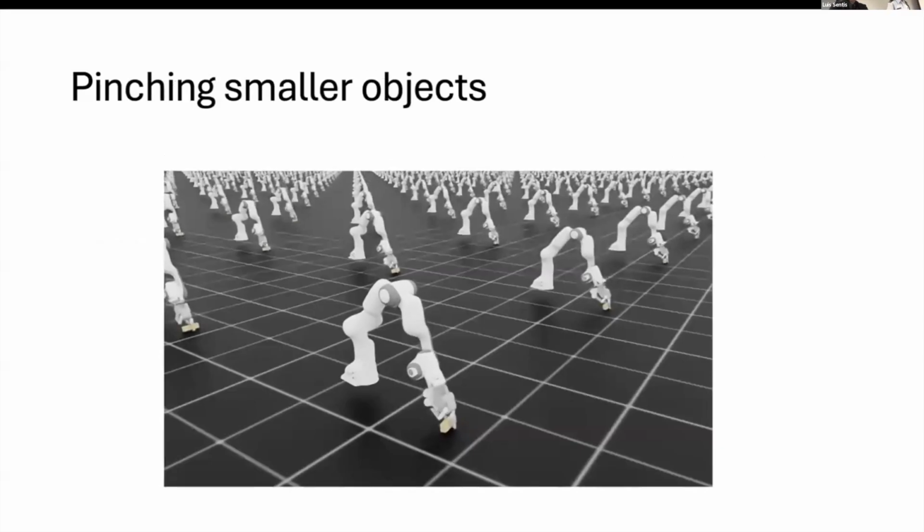And then here you can see, we managed to get the 2 fingers to pinch the object. The reason it's shaking right now, which is kind of hard to see, is because of the lift reward. It's actually balancing the Jenga block onto its diagonal edge because that gives it just a little bit of reward. And so we are able to get that fine pinch, fine grasp. But when we were doing this iteration, we needed some work on the lifting, getting that curriculum set up.